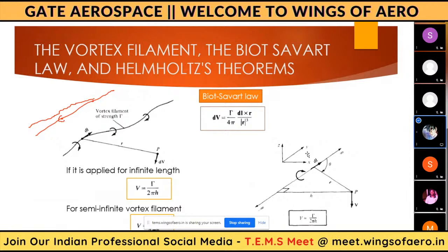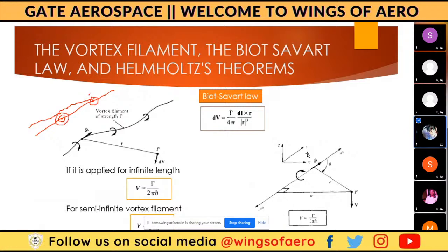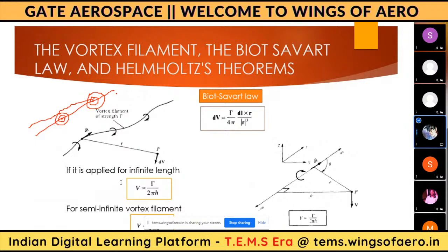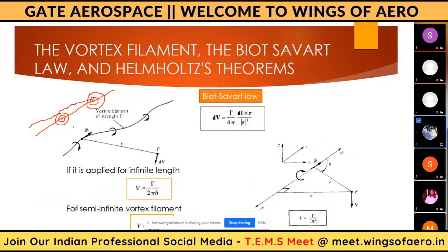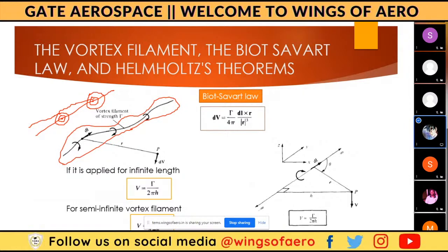That is, vortex flow is a concentric flow induced over a specific point O, or whatever point you consider, whatever notation you give. So a straight line having vortex flow over some point is called a vortex filament. But in general, the vortex filament won't be in a straight line. It will be curved. That's why here I am showing the vortex filament; you can see it is curved.